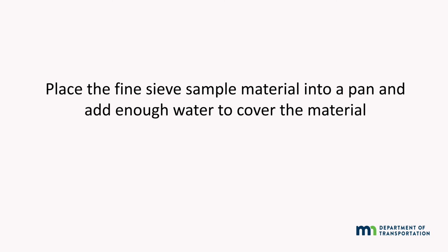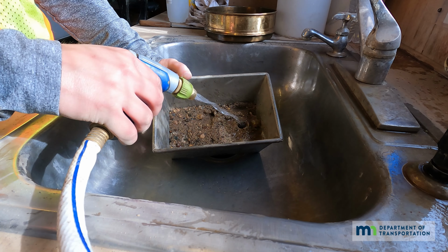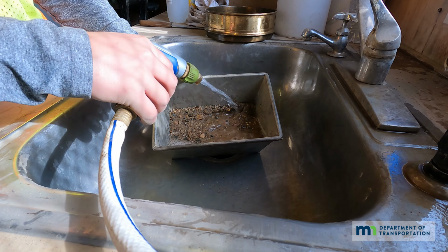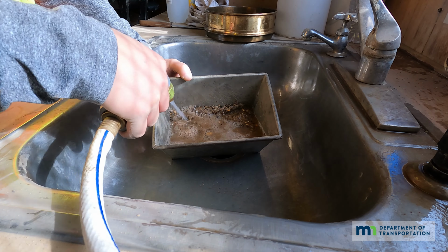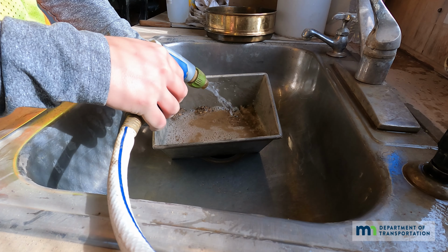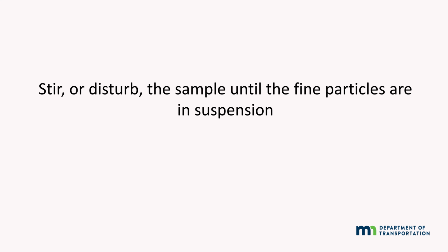Place the fine sieve sample material into a pan and add enough water to cover the material. Stir or disturb the sample until the fine particles are in suspension.